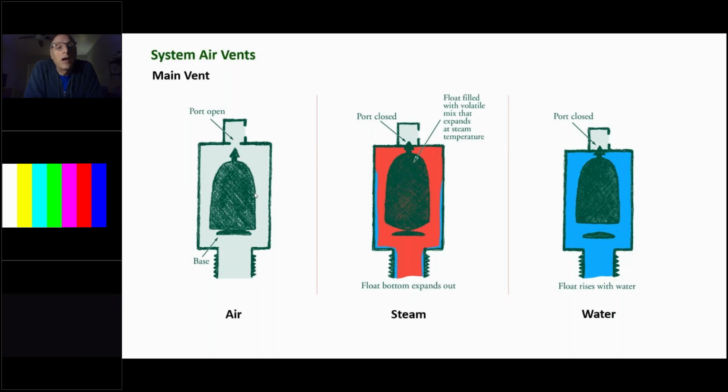At that point, I would recommend you find a Gorton, and Gorton will not sell to distributors. They only sell online. So you can go directly online and buy a Gorton vent that would do equal to four number 75 Hoffmans. It'll evacuate the same amount of air that four 75 Hoffman vents will.